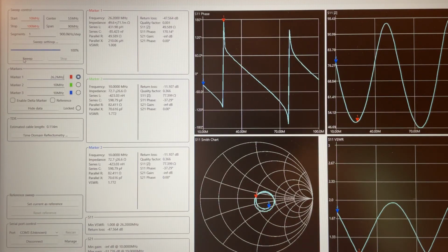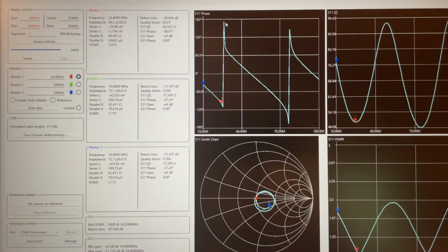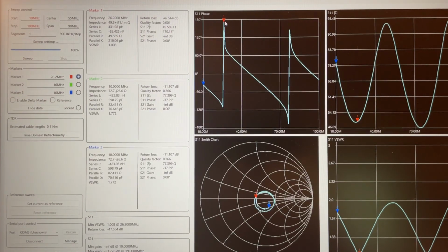And it pretty much shows what you just saw on the slide. So again, we can't get to zero because of the resolution, so we go to minus 120, it's 24.4 megahertz, and we go plus 180, it's 26.2, so if we average both of those out, it's 25.7, which is here.